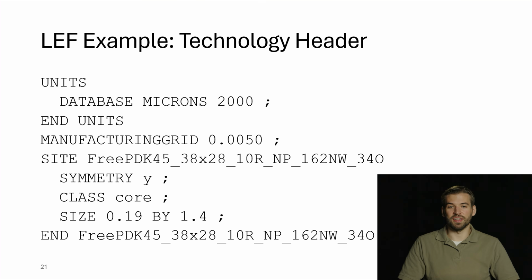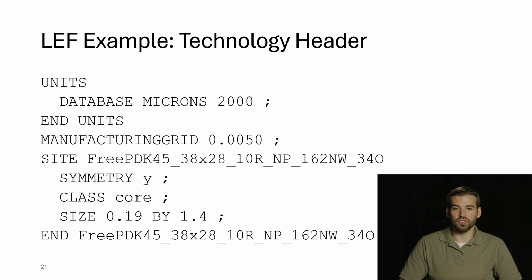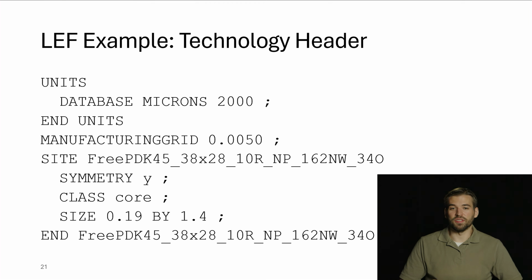Additionally, the brick can be any size as long as the width and the height are a multiple of that bump pitch. So that's the same concept as a cell site in LEF. This cell site defines the X pitch and Y pitch, and in order to fit properly, it requires all masters to be a multiple of this rectangle. This site is also required to have a name because there's no reason why you can't have another cell site with different dimensions, which is the basis for a different library of masters.